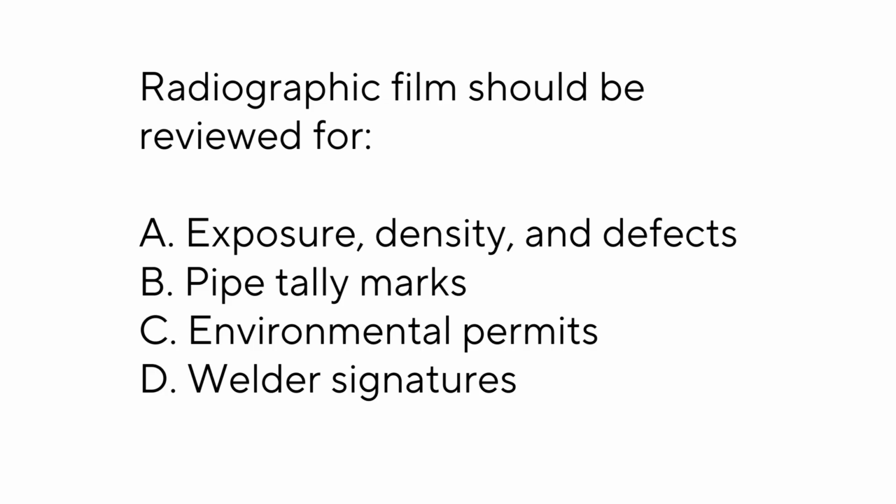Radiographic film should be reviewed for: A. Exposure, density, and defects, B. Pipe tally marks, C. Environmental permits, D. Welder signatures. Answer: A. Exposure, density, and defects.